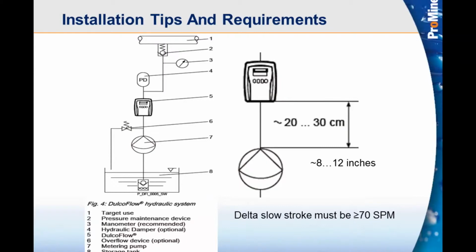That's where that pulse is ideal for the Dulcoflow to use that flow going through, that pulsing flow. And again, it's before the pulsation dampener, which is again in line with the output of the pump as always. Before the gauge and before the injection valve. We also want to regulate the back pressure. Back pressure changing can change flows going through the unit. We have found that about 40 psi minimum is an ideal pressure for the Dulcoflow.